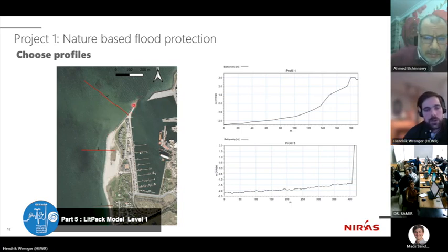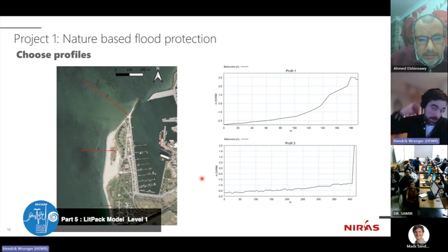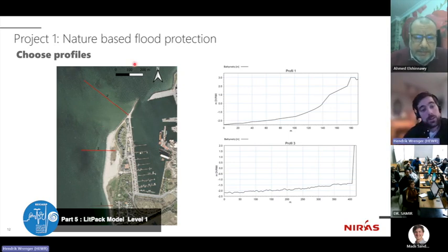and that's why these positions were chosen. The one is the orientation, right? These three are sort of linear. We can draw three lines with their three characteristic orientations. And then the other difference are the profiles themselves. So how steep the slope is, and then also here in the north the structure, as I said. So this is already one engineering choice that we need to make, right? What is the situation? Where do I need to place profiles? And sometimes it's actually iterative.